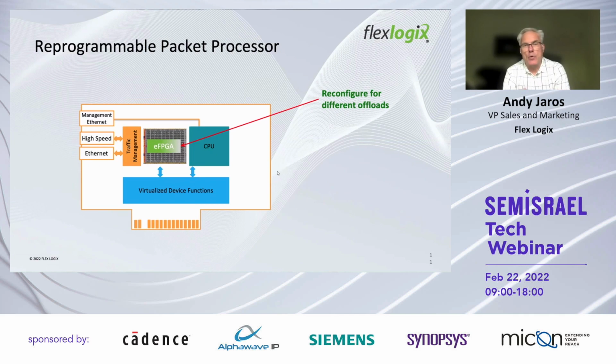Moving up the performance requirements is using embedded FPGA for packet processing. Many NIC applications require looking at specific bits in a wide data packet and performing some type of calculation prior to sending the packet on to the next stage in the pipeline. The specific bits that need to be modified change from application to application, necessitating programmability.